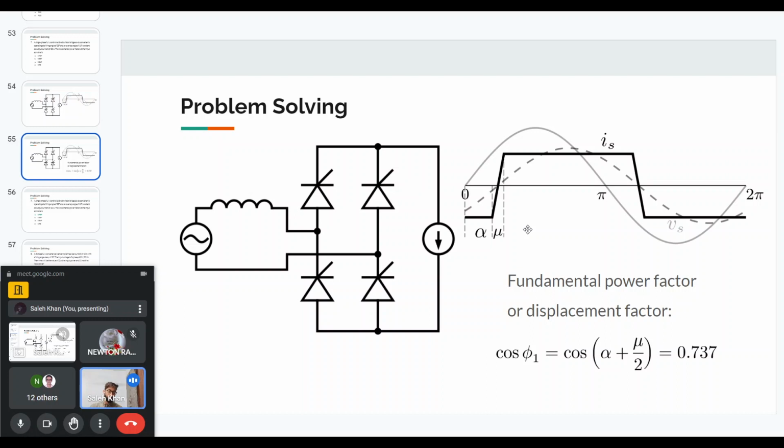So that means the THD will improve. Because of the sudden changes in the current, or a peaky current, that is where we have a high THD. Including an inductance will basically filter out some current. It will act as a filter and it will improve the THD.